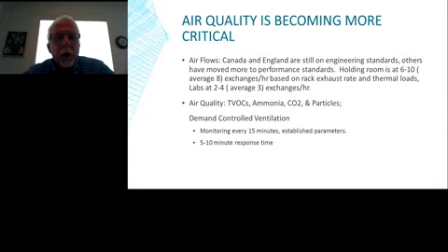Holding rooms are at about 6 to 10. The average is 8 in terms of room or air exchanges per hour. And this is based on the rack exhaust rate and thermal loads. Labs tend to be at about 2 to 4, the average of 3 exchanges per hour.